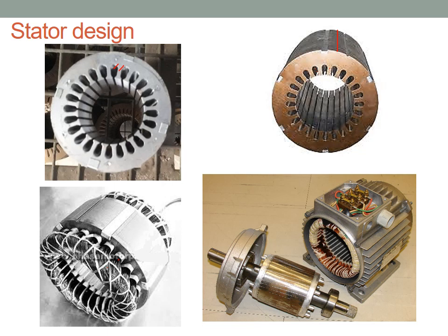When you give the three-phase supply to this winding, a rotating magnetic field is produced in the air gap. Actually, in the stator there are no physical poles existing. The type of winding creates a rotating magnetic field when supply is given. Now you can see this stator core is inserted in the frame. This is the core, and the windings are terminated at the terminal box, where you can give input supply to the winding. This is the rotor, and this is the stator.